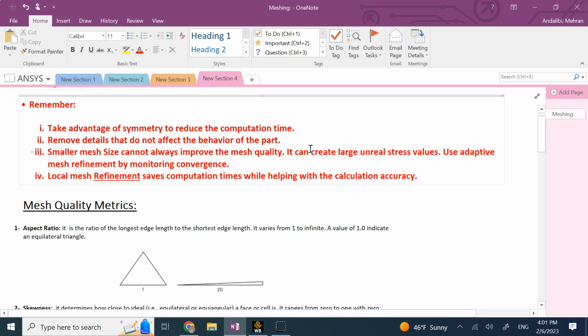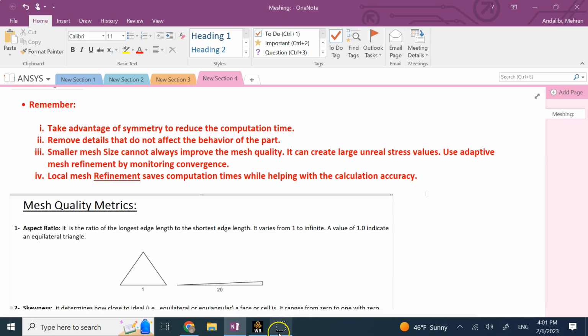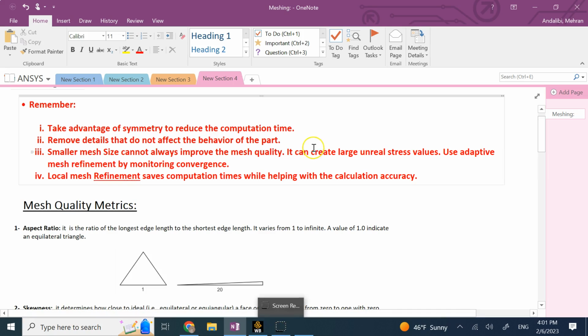Somebody who has no knowledge of finite element, when they are looking at the safety factors and trying to design, might look at some very large number in maximum stress. While it does not make sense theoretically to have such numbers, they just trust the software because it generated such big numbers. And they don't go and look: right above a very small element, I have applied a huge local force, and that causes a singularity. So you have to be very careful about that.